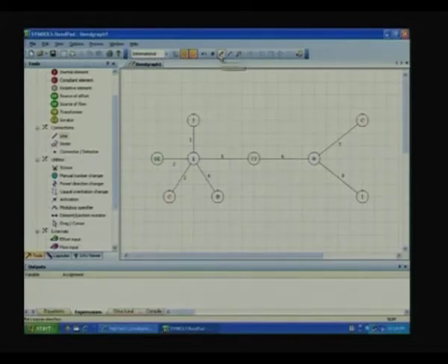Now, here is a power direction that can also be assigned automatically by the computer. So, press it, it gives the power directions. Can you see? Is it visible? Okay. So, all these power directions, just check if they are correct. AC gives out, all these take in power, transformer has the power to go through, these are all right.